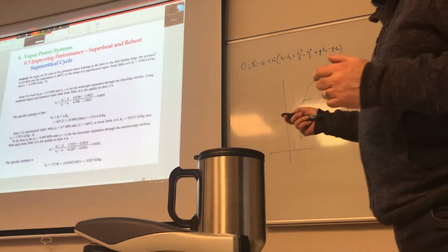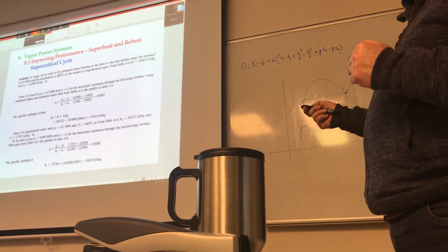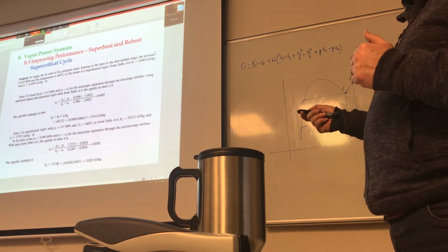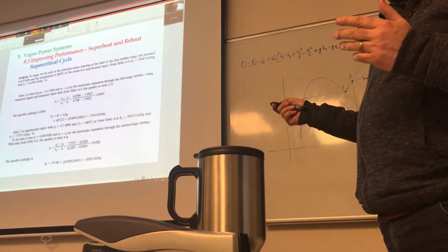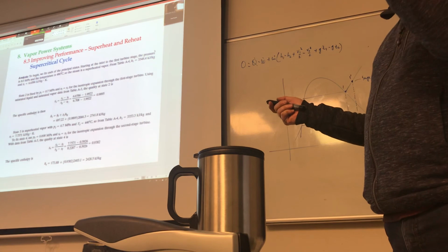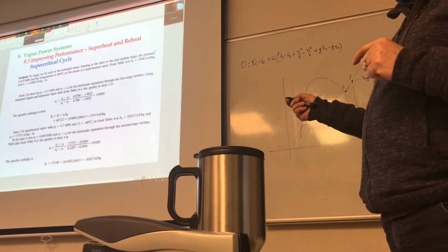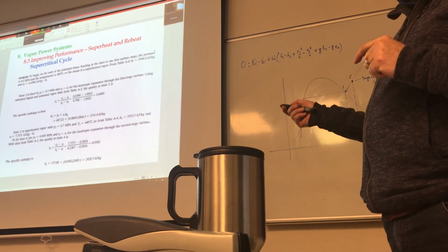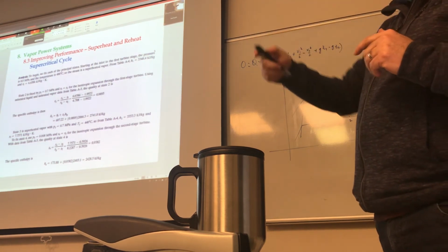So, to begin, we fix the principal states. Of course, for the initial state, which is in the superheated region, the pressure is given and the temperature is given. You get those two, you go to table A-4, boom. You can read immediately the value of h1. Why do you need the value of s1? Because remember, you have an isentropic process, right?